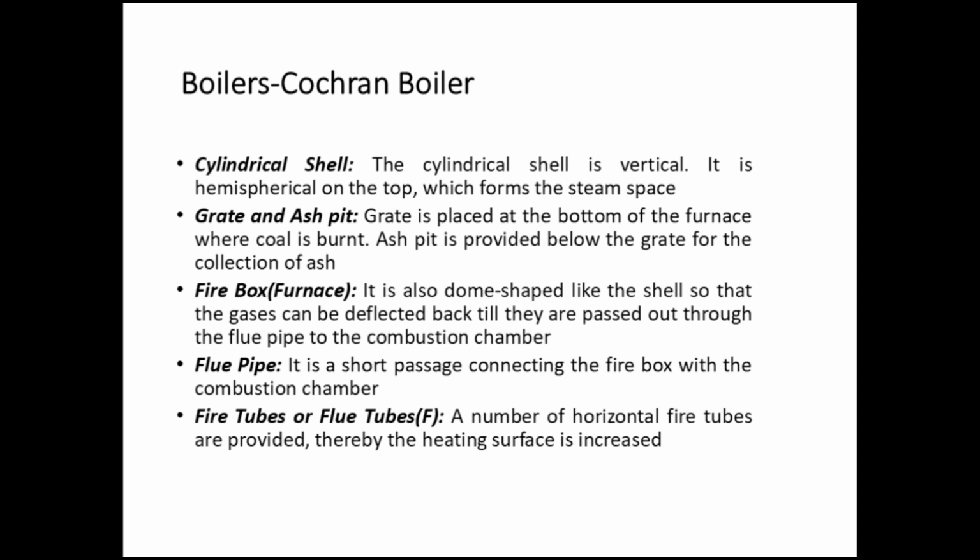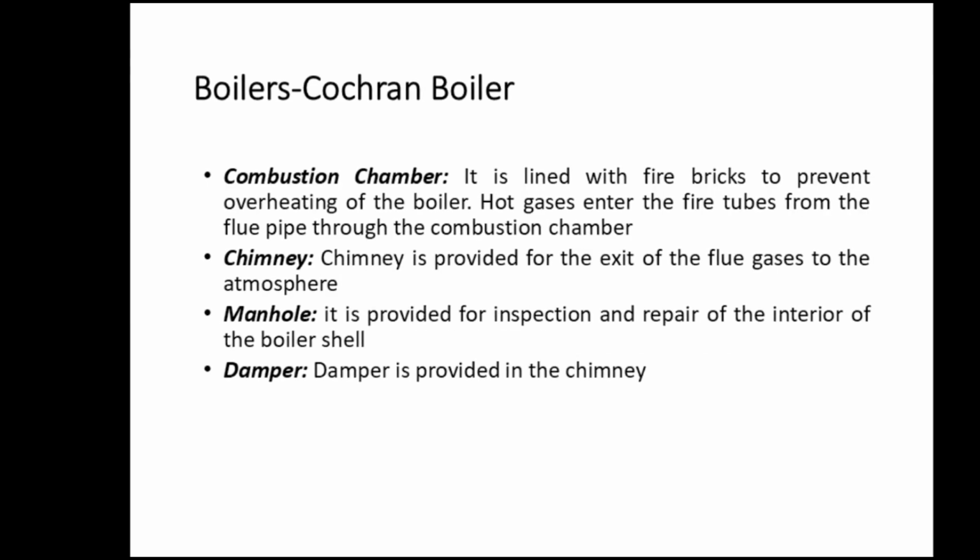Firebox furnace. It is also dome shaped like the shell so that the gases can be deflected back till they are passed out through the flue pipe to the combustion chamber. Flue pipe. It is a short passage connecting the firebox with the combustion chamber. Fire tubes or flue tubes. A number of horizontal fire tubes are provided, thereby the heating surface is increased.